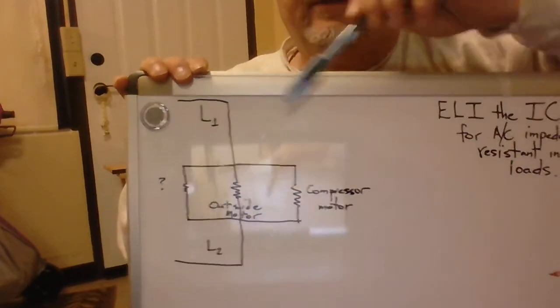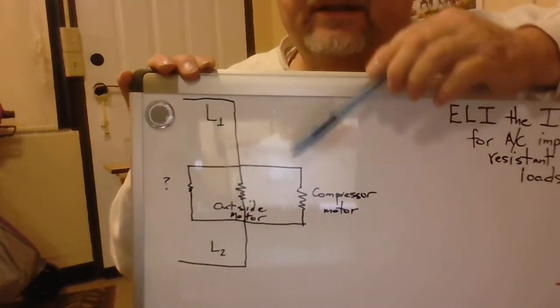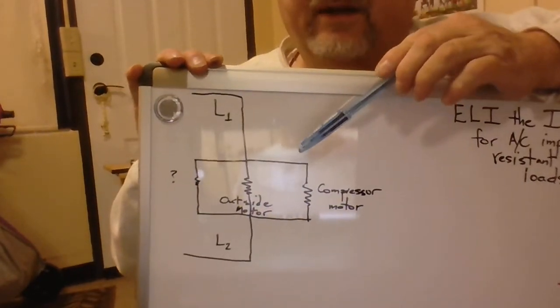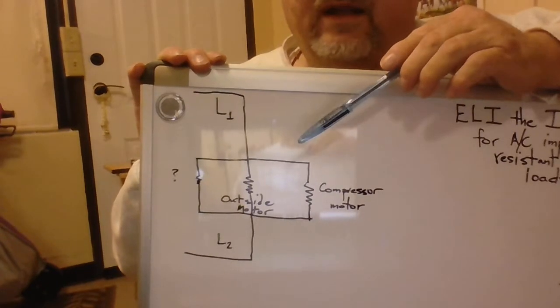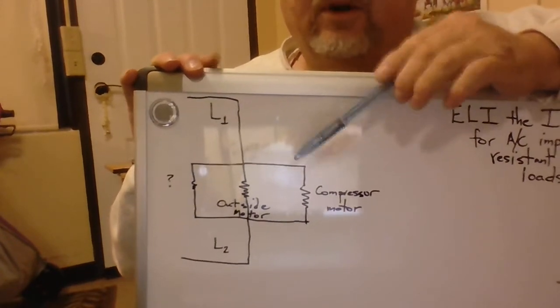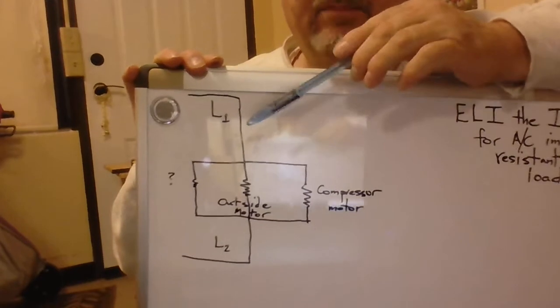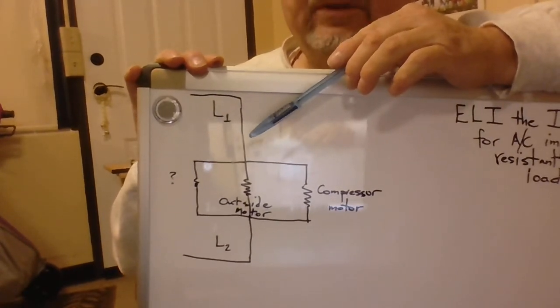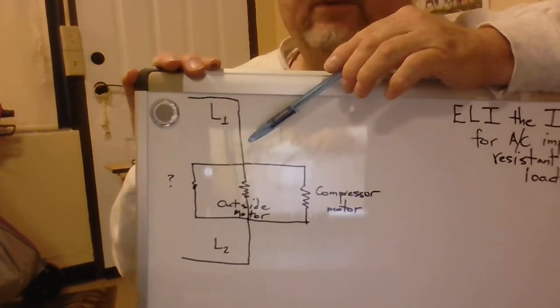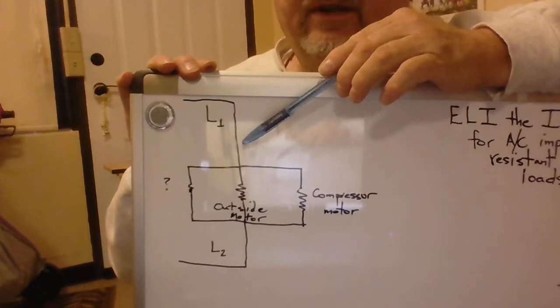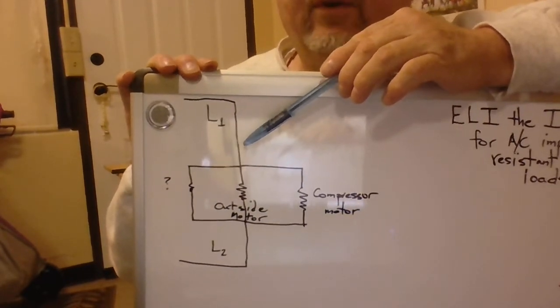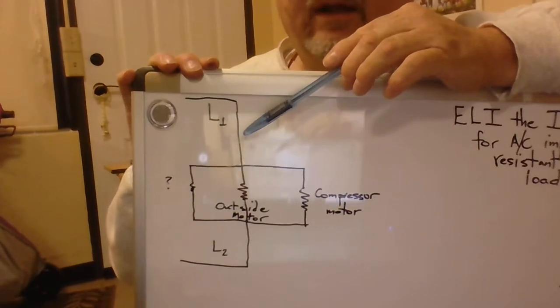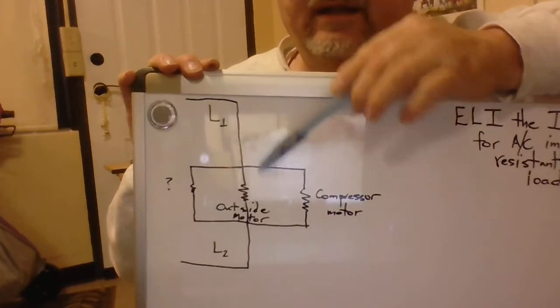So this is why a tech has to understand the series parallel circuit and what impacts it in the most bizarre way, because this is not a common problem that you're going to see every day of the week. But it was certainly something that was eradicated once I taped up and secured the insulation so that there's no amp draw at that point forward. And then everything settled down.